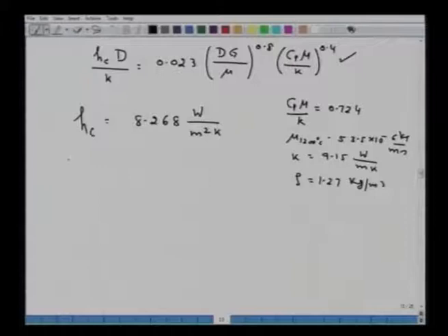So, all that you have to calculate is the heat loss by convection. So, heat loss by convection Qc will be equal to Hc A into delta T, and all values are given. So, you are getting 2976 watt per meter length of the pipe, whatever the flue that is given to you. So, that is how you will calculate.